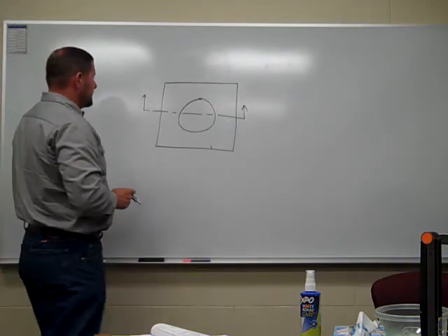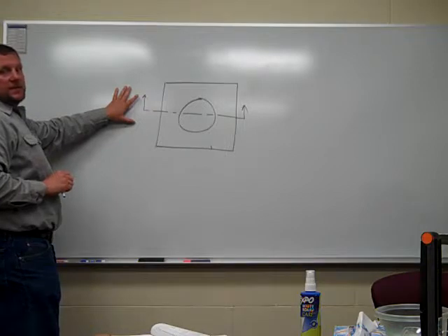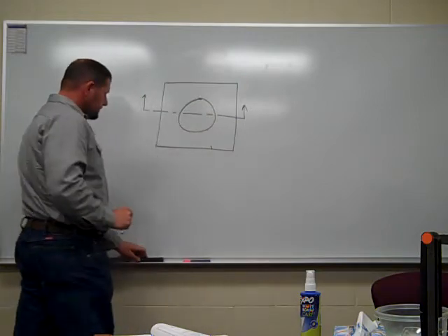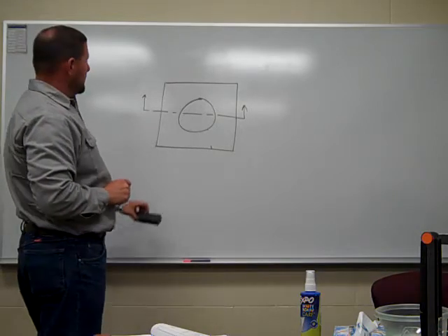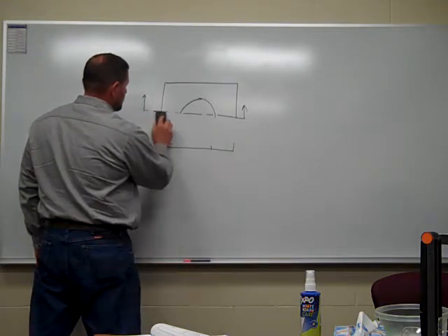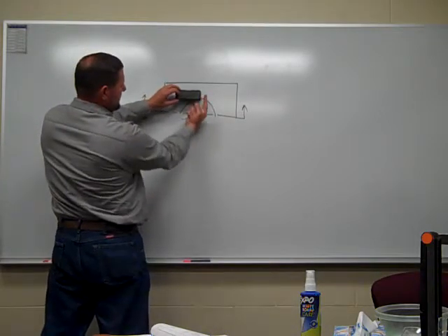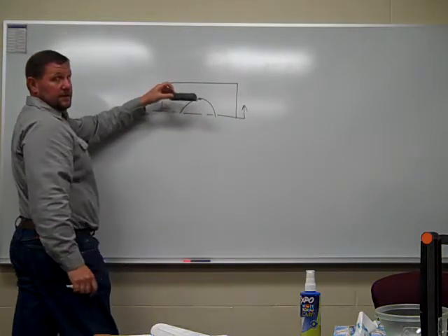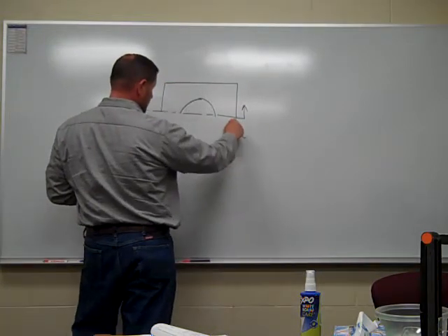So what are we doing? A good way to explain it is, let's say we take this part, we cut it in a bandsaw right here. The arrows are going to determine what view we're looking at. Basically, this whole bottom half of this object is erased, and we rotate it because we want to look at this side of the object pointing up. So we want to look at this view, and it's going to rotate it. That's what it's doing. But this is where it's getting cut. That's what that cutting plane line is used to do.